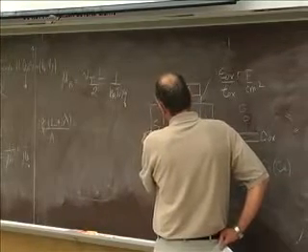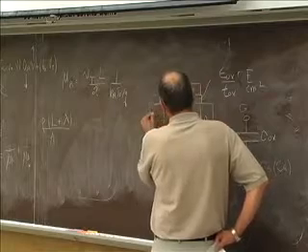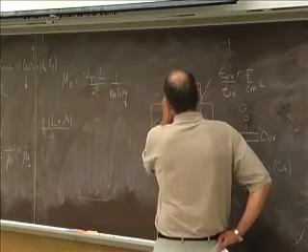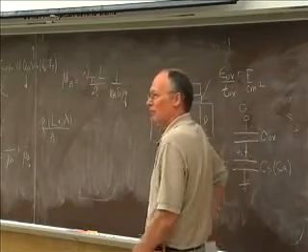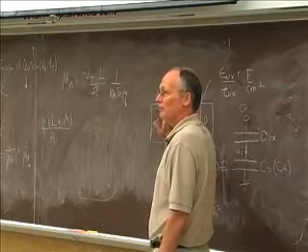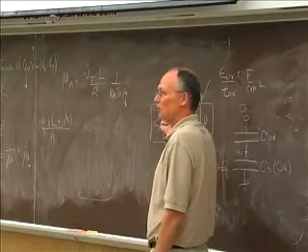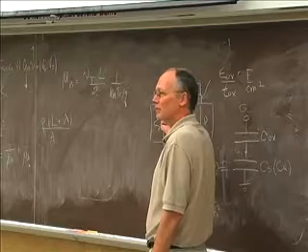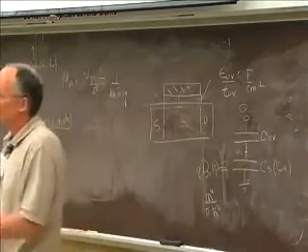What we're doing is electrons are coming in from the source, and we have this top of the barrier. We're populating these states with a Fermi level according to the band structure at the top of the barrier, which we're thinking of as the beginning of the channel. So it's the effective mass at the top of the barrier, right? We're assuming we know the density of states at the beginning of the channel. Is that right? Yeah.